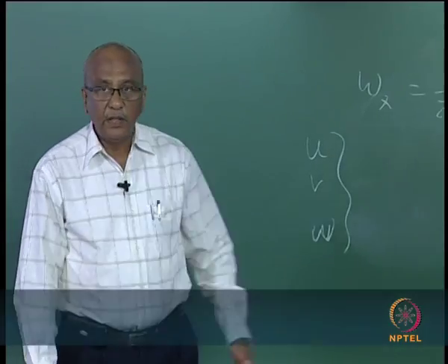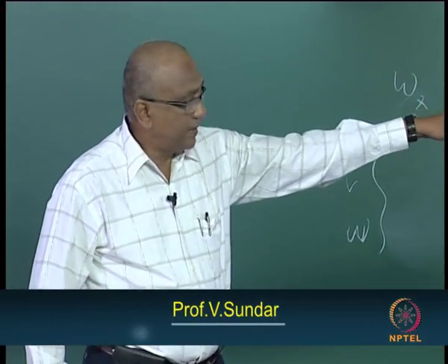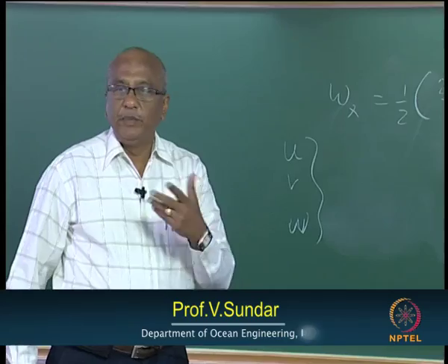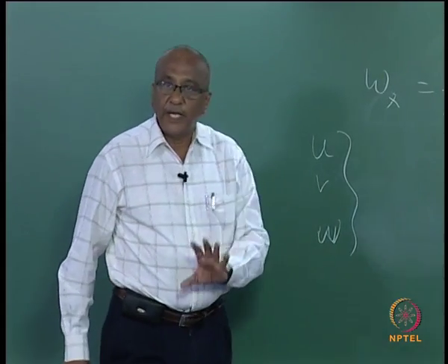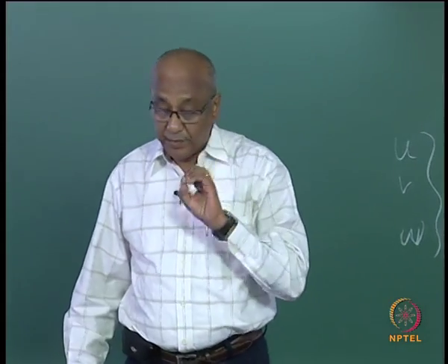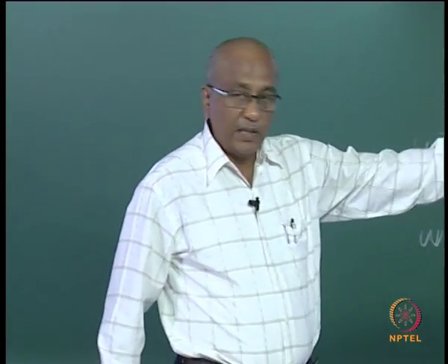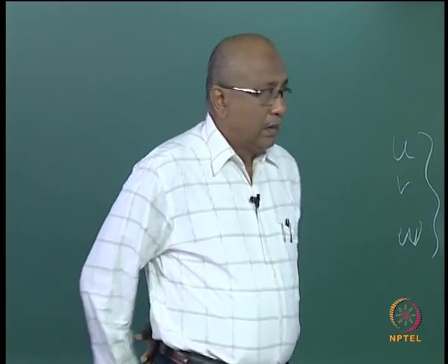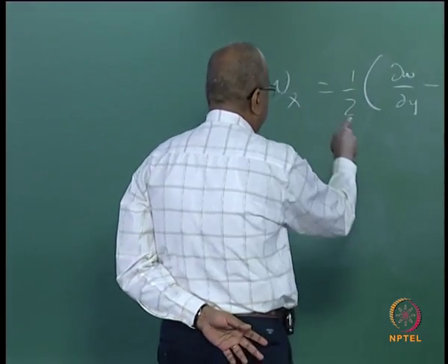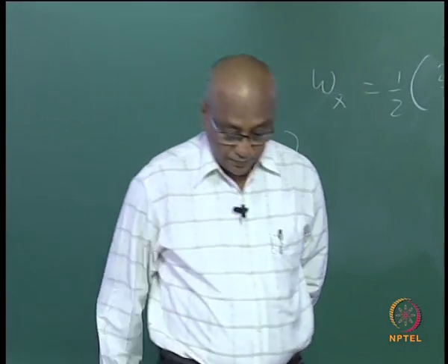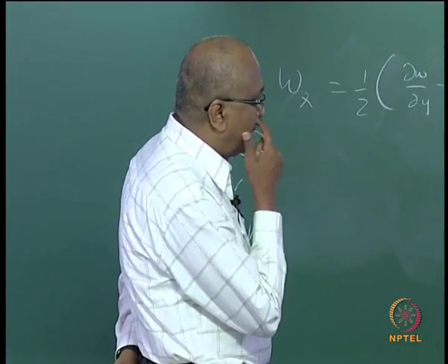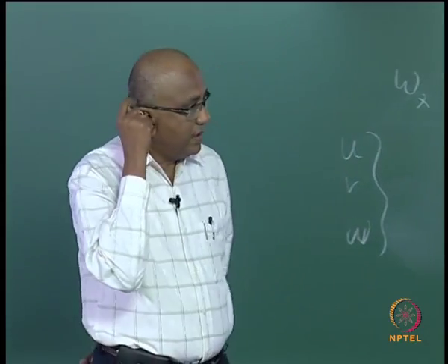Then with this differentiation, using this relationship, you will be in a position to find out whether the flow with that kind of velocities can be termed as an irrotational flow or otherwise, by simply trying to get this relationship through. Is that all right? So u, v, w are the velocities in the x, y, z directions.